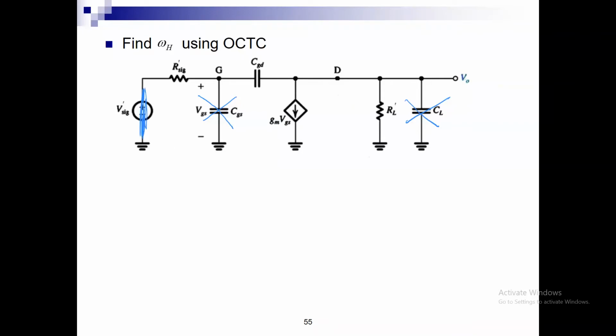So all of a sudden, I will end up with this capacitor that remains. This is the only complex case that we will see. If I want to put Vx instead of it, and this is the current Ix. Typically, the complex capacitors that you see are those that sit between the input and output, so CGD is going to be complex. The others that sit either only at the gate or only at the drain see simple conditioning. And we will look at the rules from the transistor perspective without flattening this way.